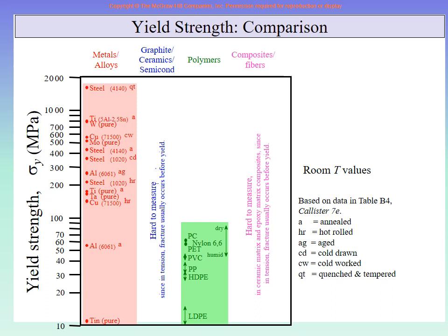Do you understand? Two different things. One is that they are very hard and very strong. They are much harder and stronger compared to many normal metals. This is one side. The other side is that they are brittle. And I tried to explain to you earlier, it is not that if something is very hard, it will be brittle or not. Something can be very small hardness and still brittle, and something can be very high hardness and still brittle. Brittle simply means what? Yes, you are right. Brittle simply means that there will not be large plastic deformation. It will not be very ductile. So that is the problem.